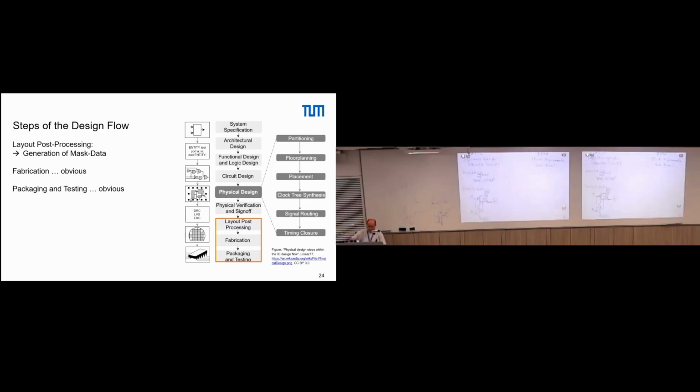Of course, you can still say, okay, give me some gate-level netlist, then you will get something like an AND gate, just as for the ASIC, with ABC, but it's not dedicated in any way to low power or something like this. It's just a logic description of what you have anyhow. Then we also don't have a transistor level. So what effectively does a NAND gate mean on FPGA?